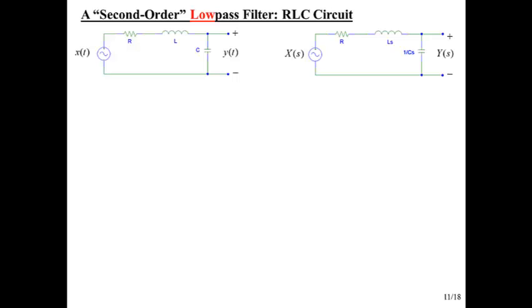All right, let's go to a second order circuit. The reason that this is second order is that it's got two energy storing devices. It's not always true. Sometimes you get a degenerate structure, but for the most part, if you count how many capacitors and inductors you have, that will tell you the order of your circuit. And the higher order you go to, the more capability you have in making that circuit do, to make very high performance filters.